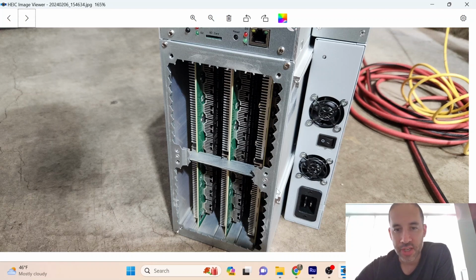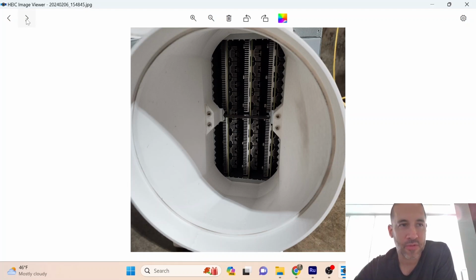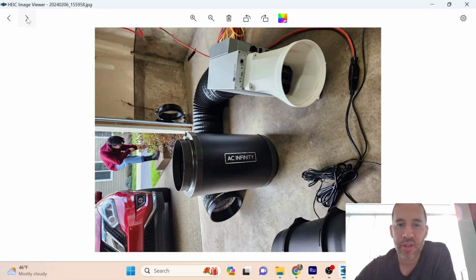And if you're worried about rigidity issues, that's not really a concern, because there's all these bends that add some rigidity to it on the perimeter, as well as the fact that you're going to be bolting your duct right back onto here, which is going to make it more rigid anyways. So there's no loss in rigidity really, and if there is, it's super negligible. Whether or not it's a bad thing for potential ingestion of large foreign objects, that is something you'll have to decide whether that's a risk you want to take or not. I personally don't have a risk of it because the inlet is in a safe place where nothing's really going to fall into it. So very, very low concern for me.